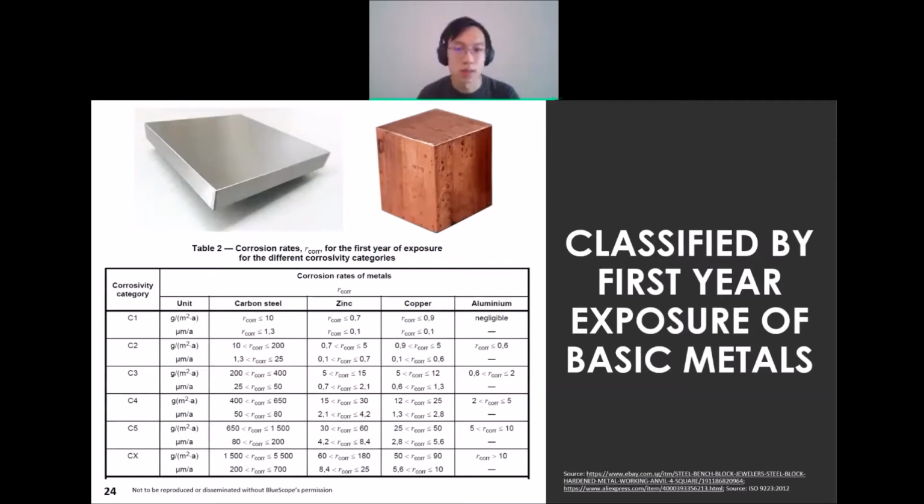And let me just remind you, because I've heard this before from someone. In this case, zinc here does not mean galvanized steel or so-called GI, right? Zinc here means a solid zinc block, right? The corrosion of this one is very different from galvanized steel, where in terms of galvanized steel, the reaction is faster because you have the effect of the galvanic reaction.